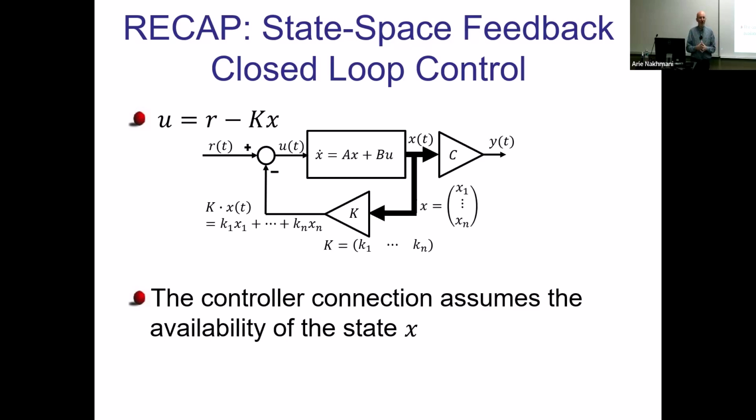But if you assume controllability, so if the system is controllable, you can move your poles anywhere you want in closed loop, and you can get practically any performance you want based on the location of the poles that you design, right? And zeros, unfortunately, you cannot move with state space feedback. So zeros stay the same in open loop and closed loop. You are not moving zeros at all in state space.